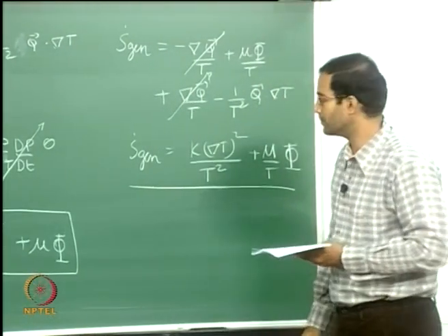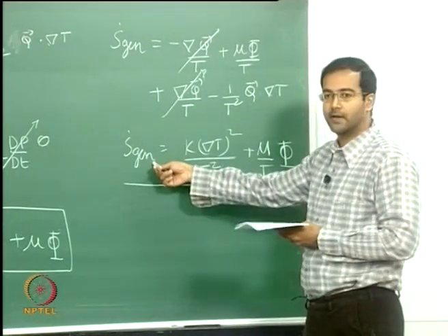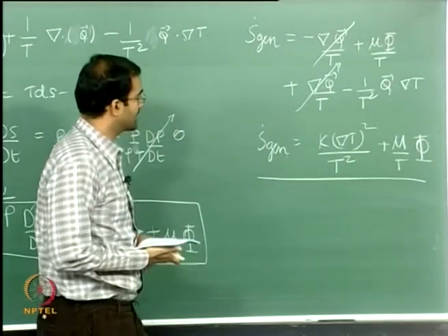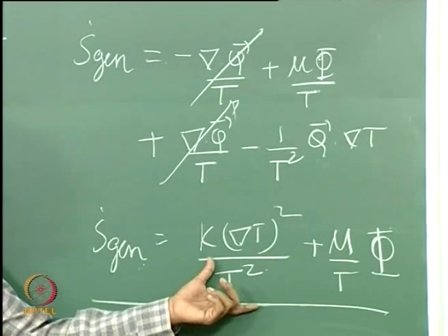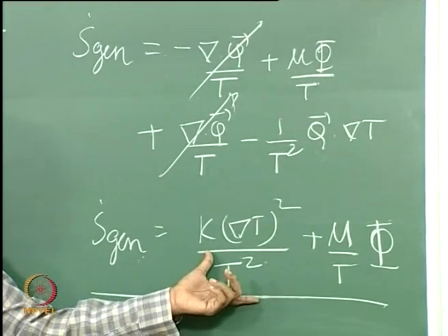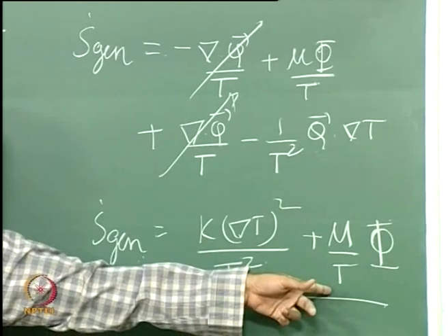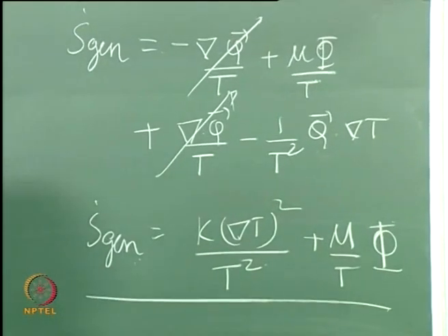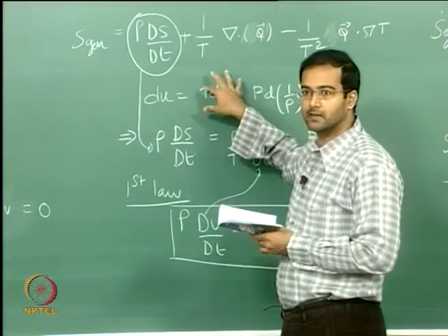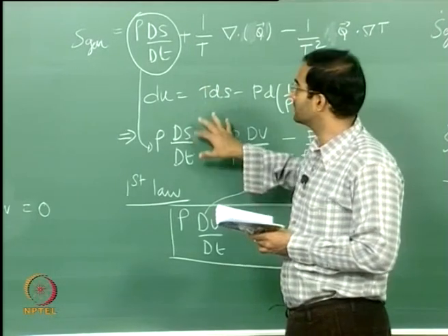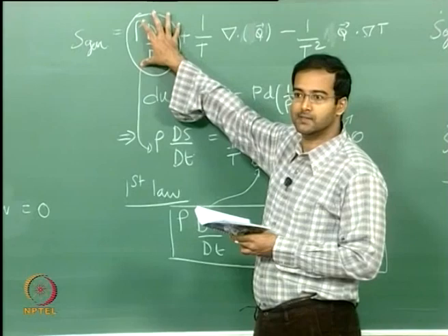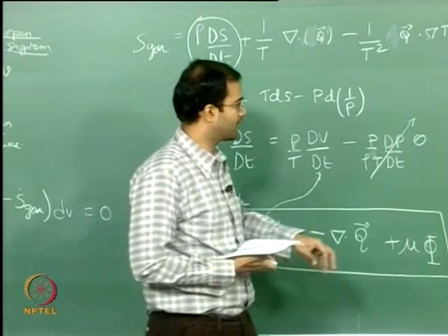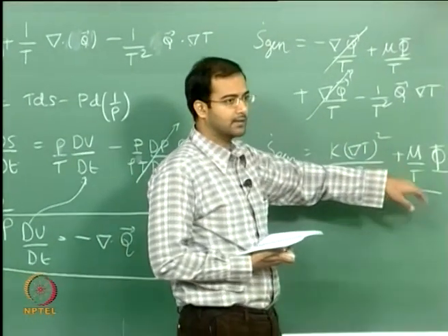So the components of entropy generation are two. One is coming from the entropy generation due to the conduction part, the conduction of heat within the system, and the other is due to the viscous dissipation. So this part till here I think it's straightforward. Only after this we apply the Gibbs law and manipulate a little bit so that we can eliminate some of these total derivative terms. So finally we write everything in terms of the heat transfer by conduction and the viscous dissipation.